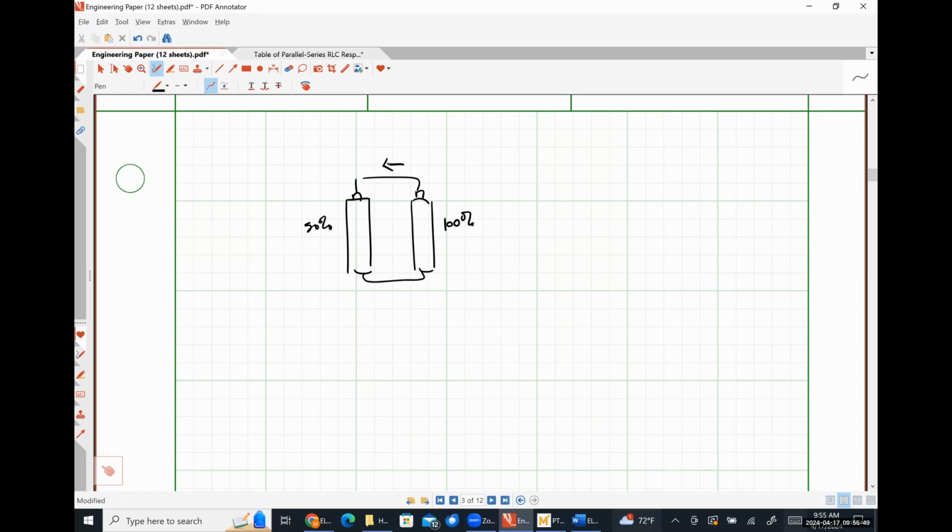So a fully charged 1.5 volt battery actually probably has closer to 1.7, and an almost discharged 1.5 volt battery probably has somewhere closer to 1.4 volts. So there's going to be a potential difference that's going to cause current to flow through that wire. So what you're going to see is probably sparks and a whole lot of heat.